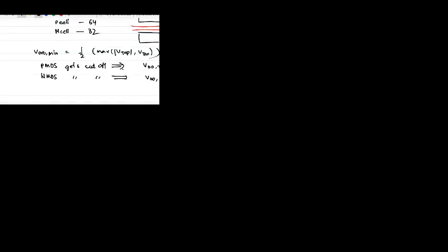So you are having this output driver, right? If you look, VOP minus VON is your output swing, right? So what is the minimum output swing it can go? You see here that VOP minus VON is equal to VDD_TX by 2. This part you get it, right? So what should we do to have a lower output swing?